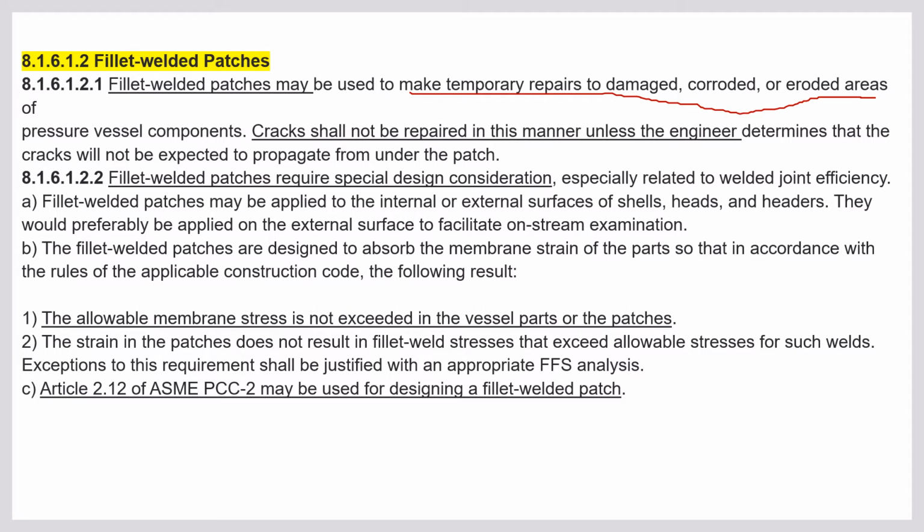So fillet welded patch may be used to make temporary repair on damaged, corroded and eroded areas of pressure vessel components. So cracks shall not be repaired in this manner unless the engineer determines that the crack is not expected to propagate from under the patch. If there is a crack and you want to repair it with a fillet welded patch, you need to contact the engineer first and take his approval. Because he has to evaluate that if you do the crack repair with the fillet weld patch, it will not propagate beneath the fillet weld patch.